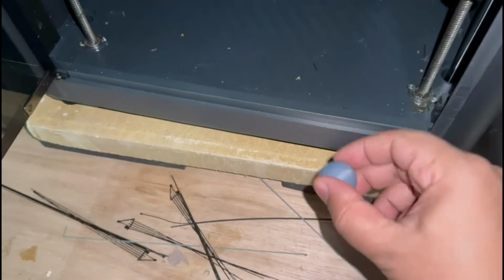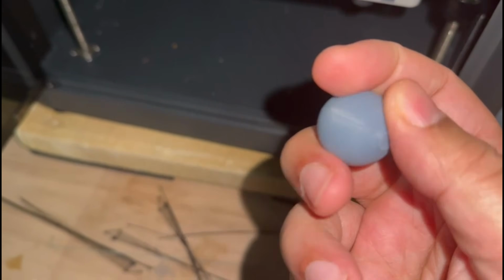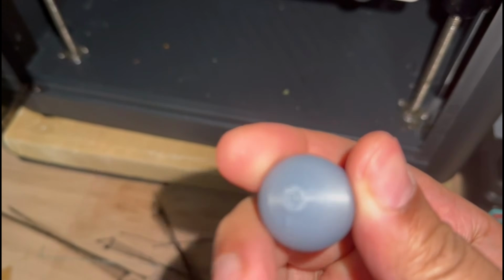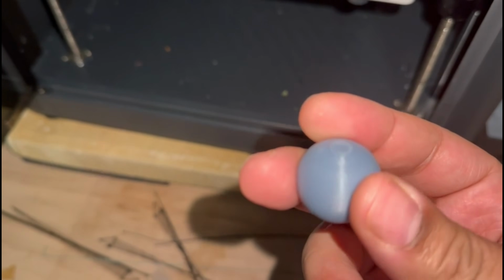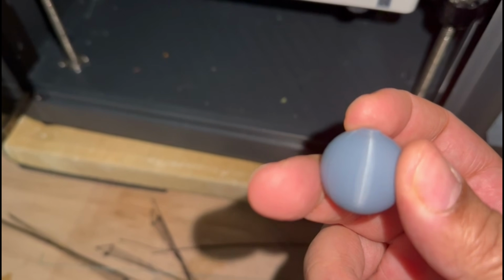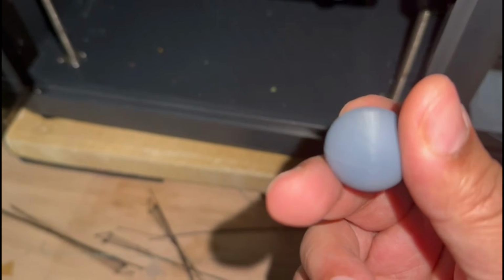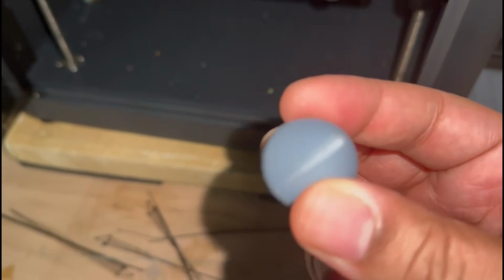So this is the sphere. Again, printed out excellently. But if you can see here, that's what I called the brim. It's actually not a brim. It's actually a part of the actual sphere. So what we might need to do in the future is, if we want to print an actual sphere, we'll have to probably surround it in some sort of support material to hold it off the build plate and to get a perfect sphere. Again, something we can look at in future episodes.